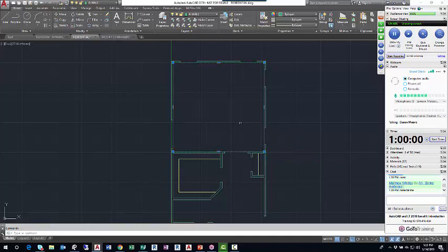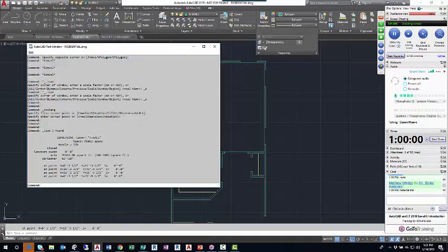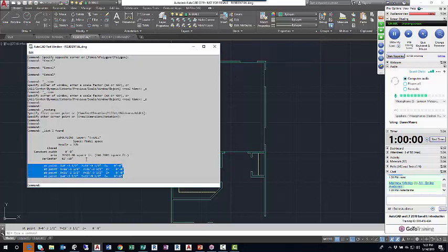With that polyline selected, if I open up the properties panel and I'll click list, that tells me everything AutoCAD knows about that line. So that line lives on a wall, and that polyline lives on a wall, and so on and so forth. And I can see the square footage is right here, 246.7083 square feet.